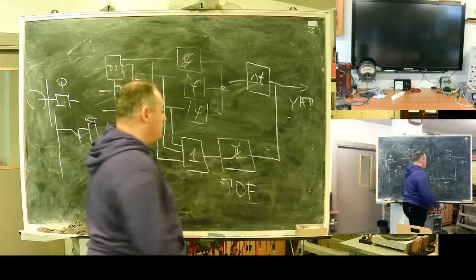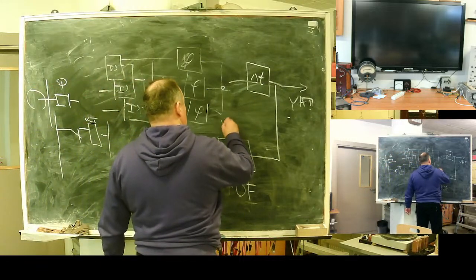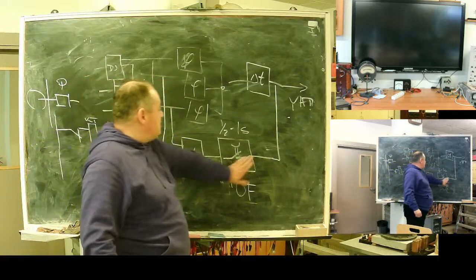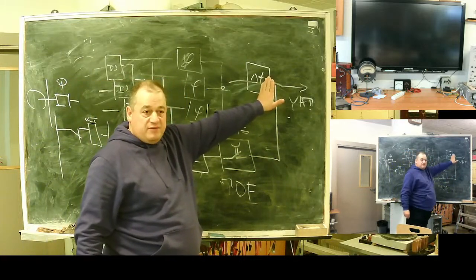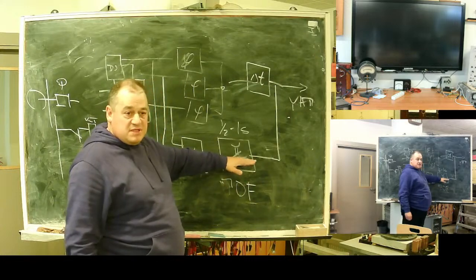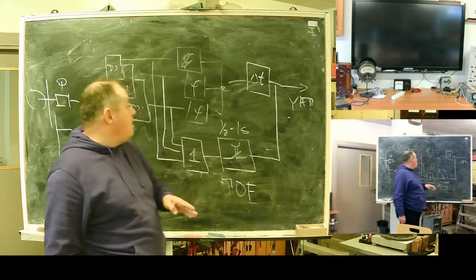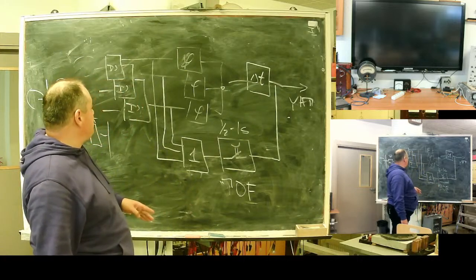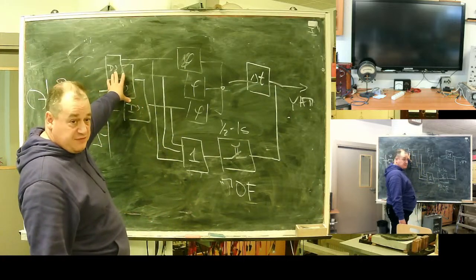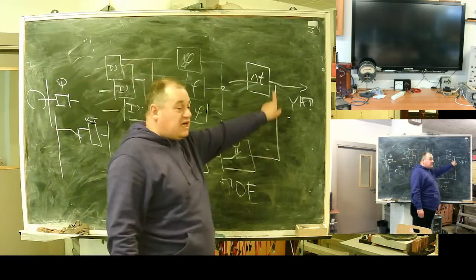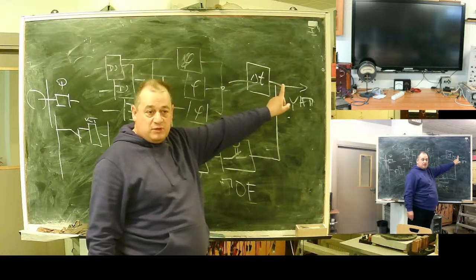But for approximately half a second, this bypass network will be active. If inside this half a second, the second sensitive zone of protection trips, the signal goes to disconnection immediately without any delay.